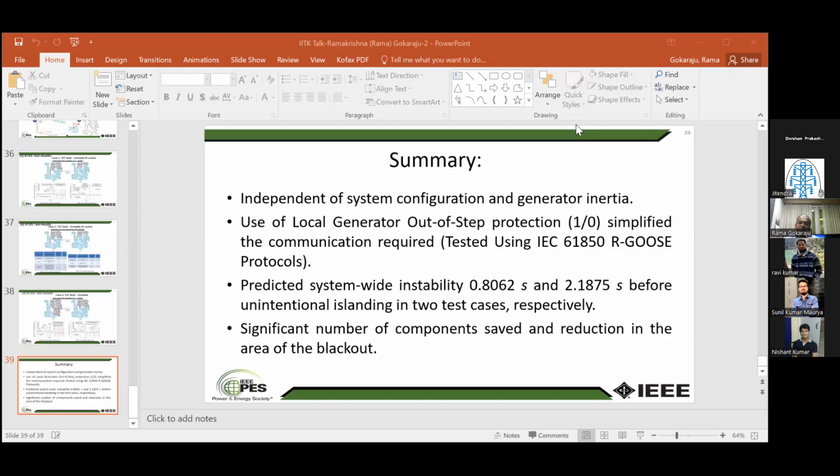There are various ways of looking at it. One way we did the analysis was using the equal area criterion in the time domain. We converted everything into the time domain. Recently, there have been a couple of publications, and there are models available representing the synchronous and the asynchronous types of renewable energy resources. So we would have to have a very good model available for the equivalenting.